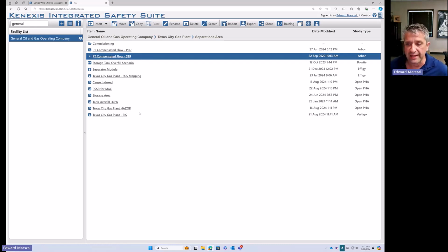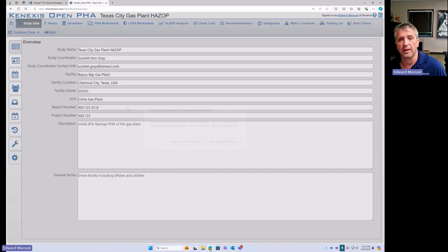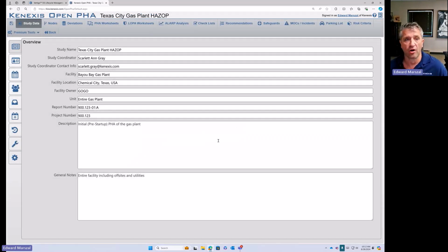The starting point in that SIS safety lifecycle, clauses 8 and 9 in the standard, are hazard and risk analysis and allocation of risk reduction to protection layers. And that is done in our Open-PHA tool for HAZOP LOPA, for PHA studies of all kinds. So there is an entire webinar that we recorded on Open-PHA that's available through our website, but let me just kind of summarize it